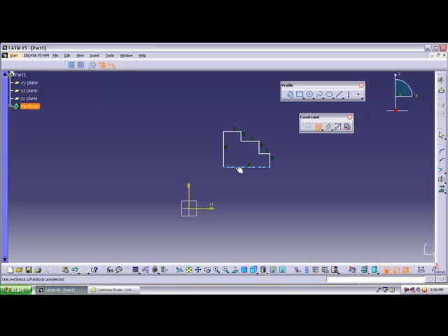We should give the height, the complete length of this line, and the complete length of this line. After that we can give the opposite two lines, or any two lines, as well as vertical and horizontal. After that, what you should do is fix where the object is in the plane. Right now the object is fully constrained.